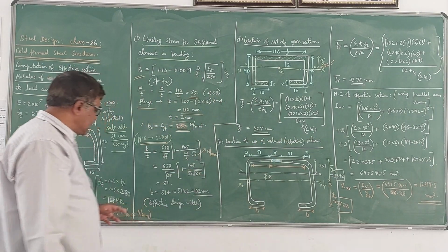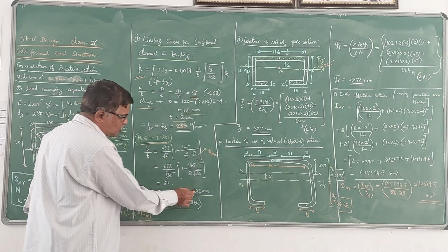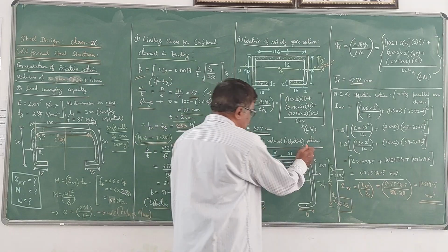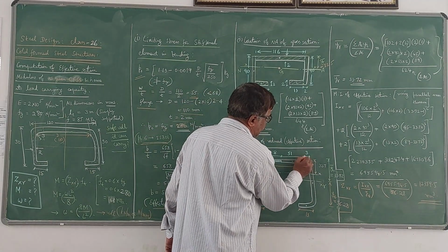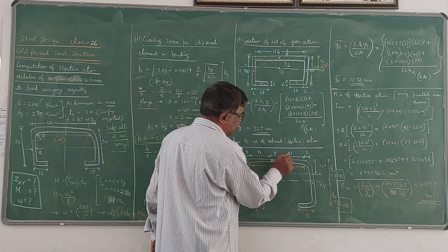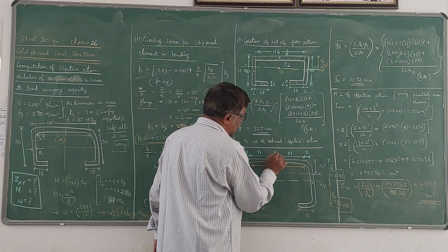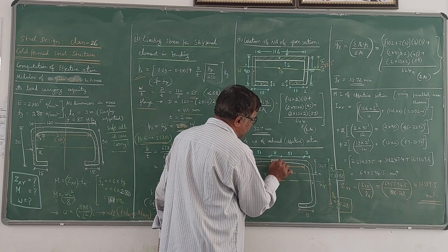So you can see here, in the case of the reduced section, the effective design width of the flange becomes 102, which is split here now. You can observe here that this is 3 mm we are going to leave for that radius, and this 51, 102 divided by 2 is 51 and 51. So this 8 mm whatever you get here becomes the ineffective portion.